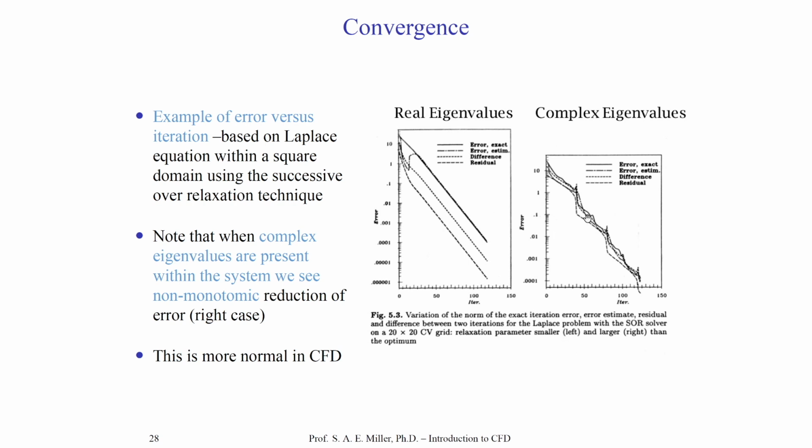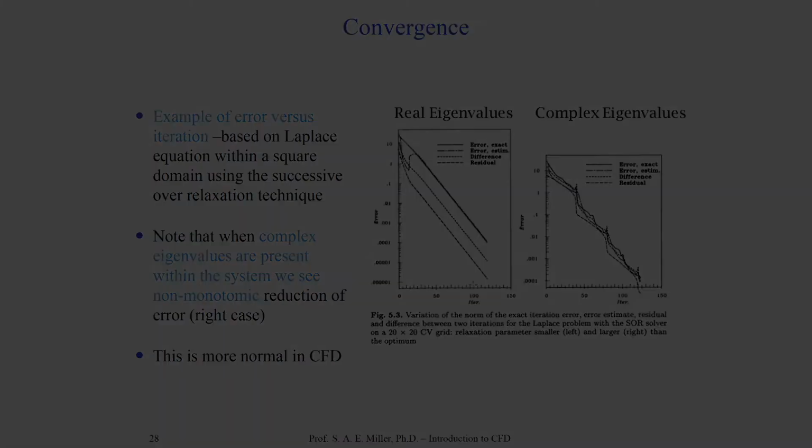So these are the types of plots you want to see in CFD. Ideally, over additional iterations, these lines would stop reducing in error. That is, as you increase the iteration maybe to 200 or 300, they would level out. That is, as the solver is making additional iterations, the solution is not improving because the error has become constant. If you see 5 to 6 orders of magnitude of reduction of error for all equations of motion, and the error or residual starts leveling out after it's been reduced by multiple orders of magnitude, then you can safely say that the solution is converged.